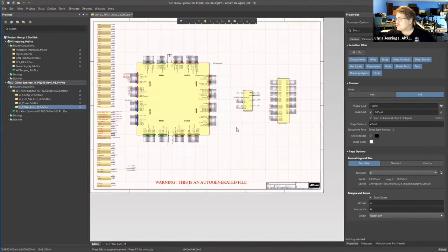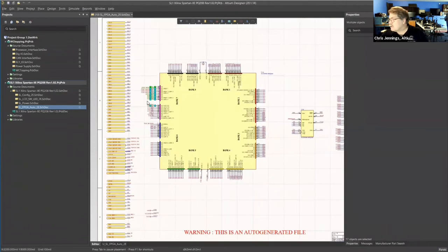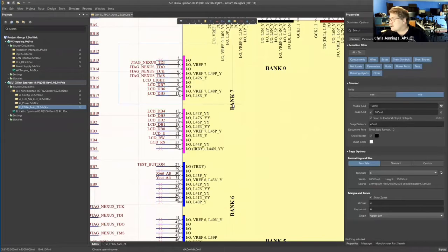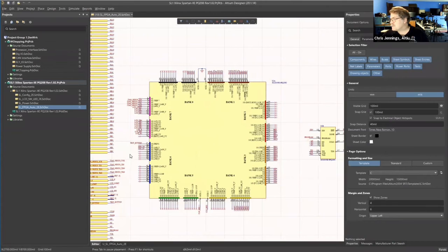You know, here's the FPGA, which is just sort of ugly in terms of how it's laid out. A lot of times you'll get FPGA circuit symbols that don't look like this big blob. This is probably the limit of what you'd want to have as a singular entity. Usually you do a multi-part. And by multi-part, that would be something like you would have all of these IOs as a block in a single entity. And that makes a big difference because now you can place those where you need in the schematic, and it's not necessarily all in a single page.